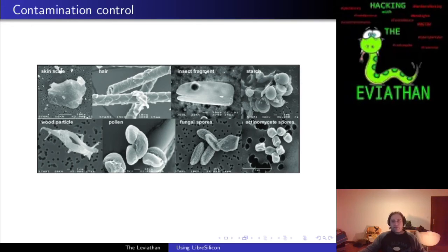You have to get that stuff out of the air when you're working with your microstructures. If you have 10 millimeter transistors or so, it's not a big problem. At 50 microns, you already cannot get anything working out of your manufacturing attempts if you have mold in your garage. So you have to make sure that the air is somewhat clean. The smaller the structures, the more impactful particles floating in the air.